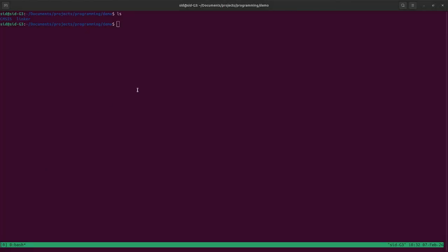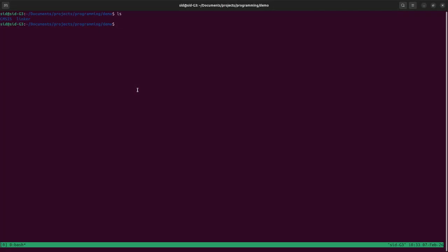So as you can see here, I've copied both folders into my project. I have the CMSIS, and then in the linker directory it contains the linker script, so you can see that right there. So you have to find the GitHub repository for the microcontroller you're using. In my case, I'm using the G431 microcontroller. If you're using an F1, you'd have to also find the F1. So you can basically Google the name of your microcontroller. If it's an STM32 microcontroller, you go to their website, and then it will show you where the GitHub repository is. You can clone the repository locally and then copy this CMSIS folder and this linker script and put it in this linker file here.